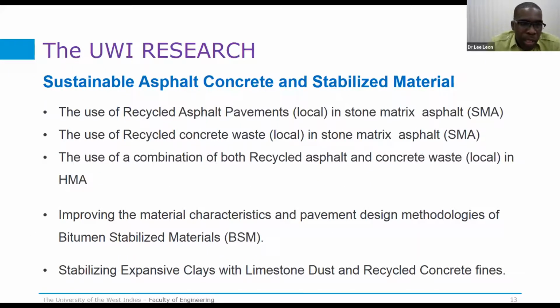We have also looked at sustainable asphalt concrete and sustainable material and stabilized material. So we have completed and also ongoing research in recycled asphalt pavements, in stone matrix asphalt, the use of recycled concrete waste in stone matrix asphalt, and ongoing research currently, the combination of these two recycled materials in an HMA dense graded mix.